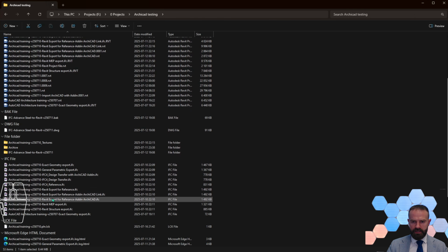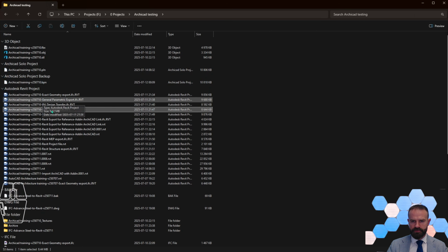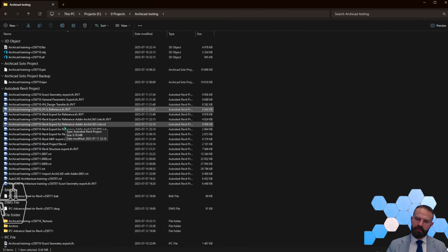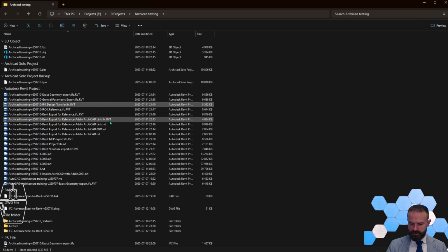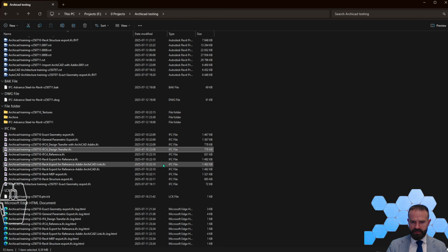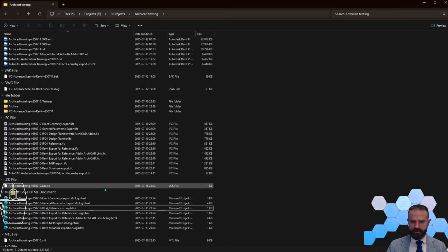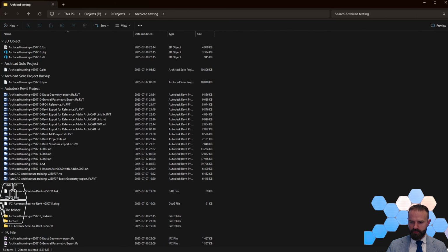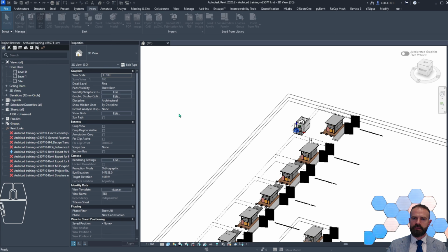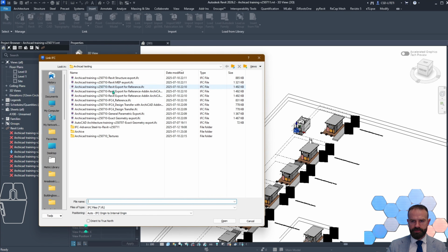So if I now link the same file, it will use this file which was created, and I will get results which were created before my modification. So the best option is just to delete both of these files, HTML and RVT files. And now I can go back to Revit and select and link the file. Another option, you can just make a copy and rename the file.